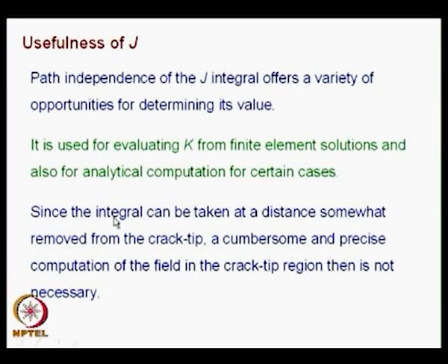Since the integral can be taken at a distance somewhat removed from the crack tip, a cumbersome and precise computation of the field in the crack tip region is not necessary. See, if you take a benchmark problem and apply the J integral, you are not going to have any advantage, because for benchmark problems you can really fill it with a very refined mesh. Suppose I have a complex structure, even modeling of the structure is difficult and you need several elements for variation